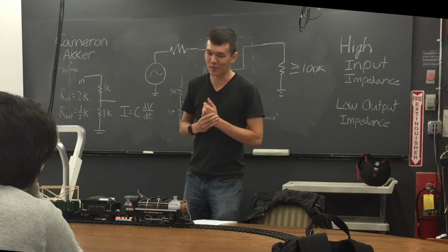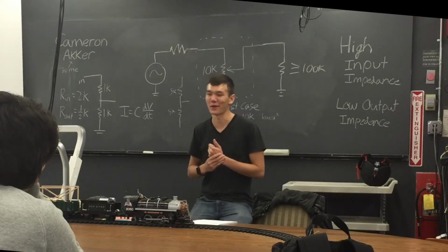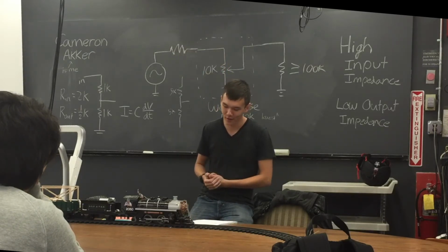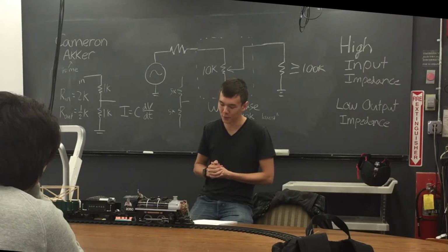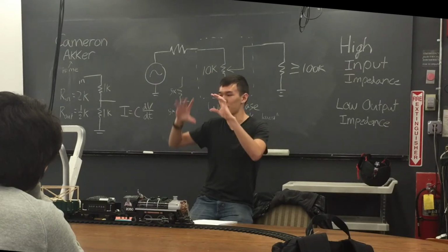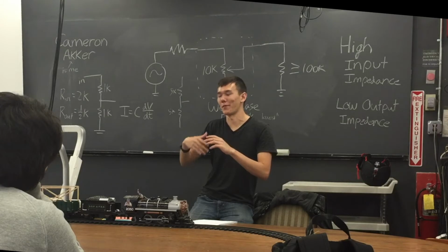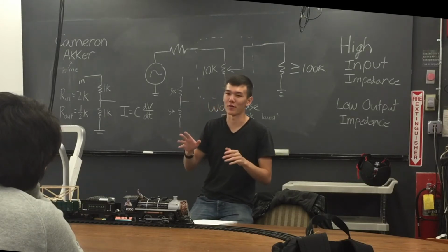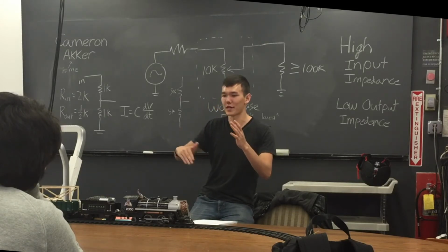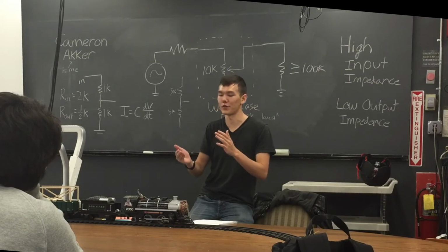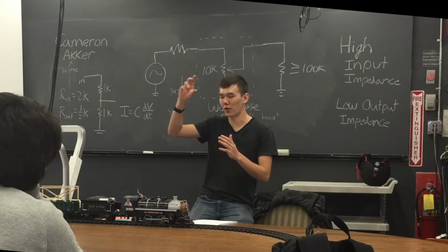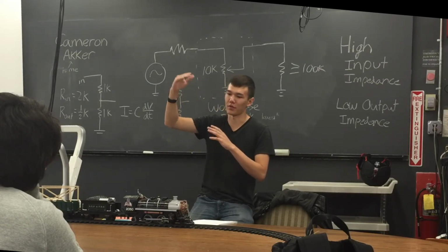Once we get to those, that'll be fun for whoever does office hours that week, because transistors are a little bit tougher. I guess the reason why they're hard is because you have to keep in mind this affects 3 terminals, but each terminal needs to have a certain condition. So I'm just going to say words, you don't have to remember any of this. The base voltage always has to be 0.3 higher than the emitter voltage. The collector always has to have a resistor to kind of set the current.